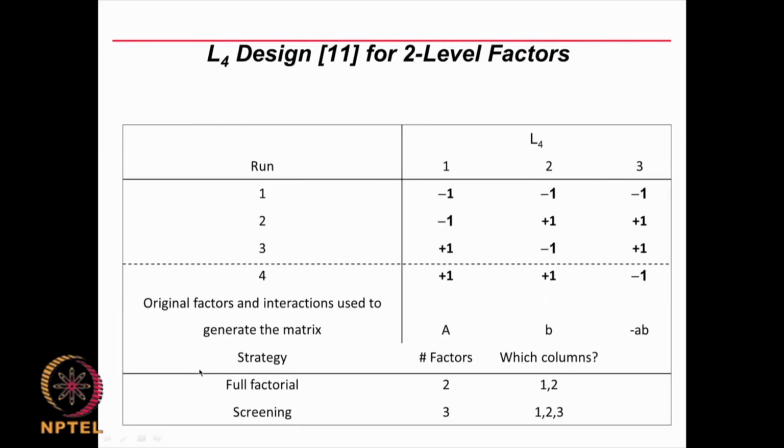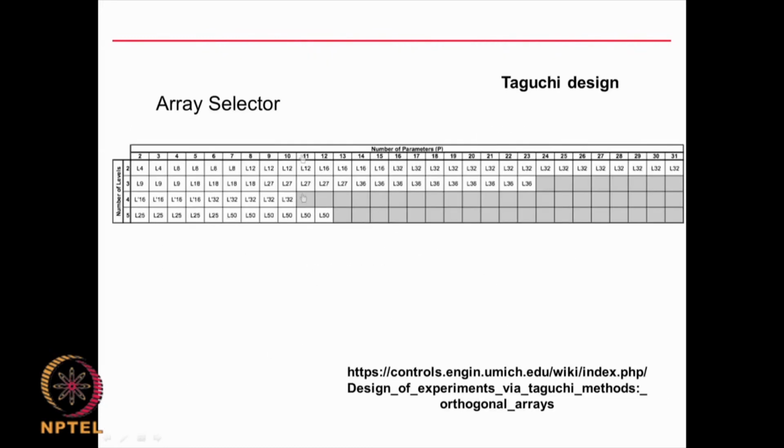The advantage of the Taguchi designs is that there are tables available. We can use different tables depending upon the number of parameters and number of levels you have. If the parameters are fewer than what is available in the table, we can ignore the extra columns. Then one important point is you need to cross check whether balance and orthogonality are maintained, because for any design you take you need to have that condition, that is very important.